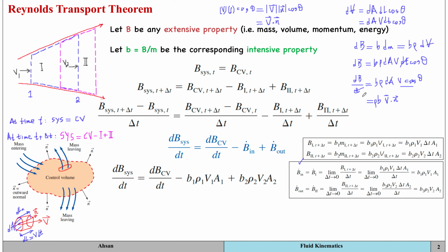Right. So this is only for just one inlet or one outlet. So what we need to do is take an integral over the entire volume, and that would give us the result for the total, or the b dot net. Another thing to notice is that this theta gives us a good relationship. If this theta is less than 90 degrees, then that indicates outflow, or the outlet, because the velocity is pointed outwards here.